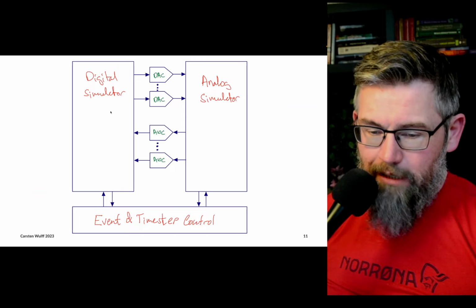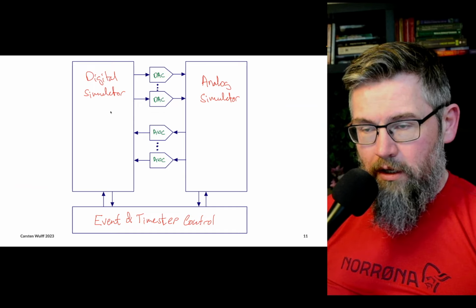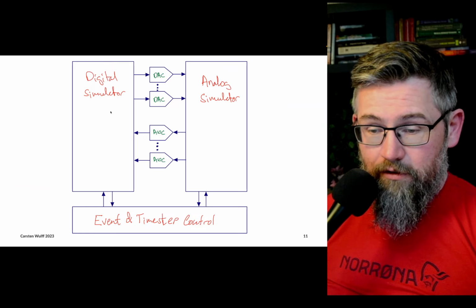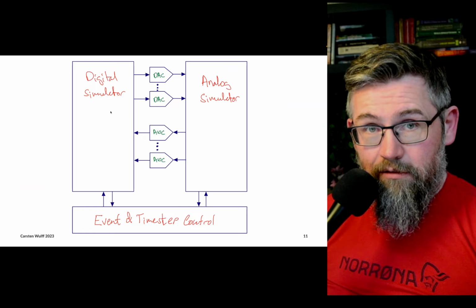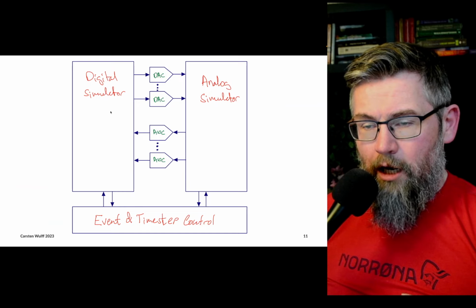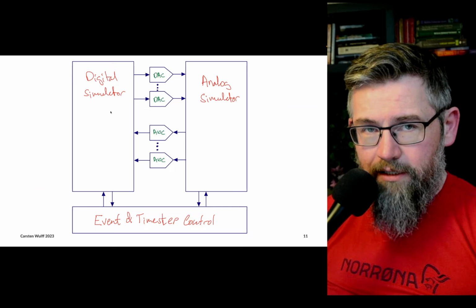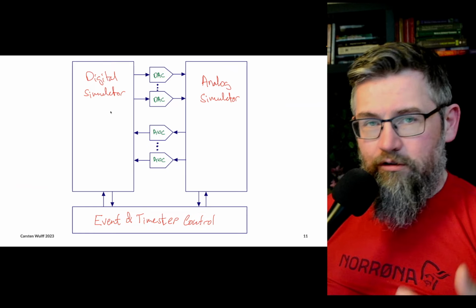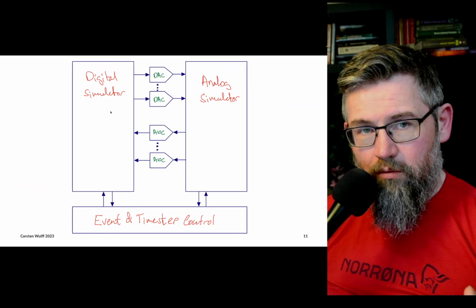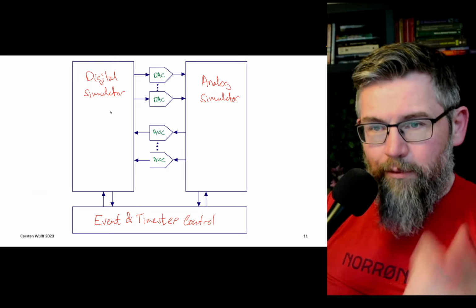And at a certain complexity level, like an ADC with a digital part, this works fine. It is a good way to verify that, for example, for a sigma delta, your decimation filter works well with your ADC. However, when you go up to chip level and you have maybe 50 analog IPs and you have hundreds of millions of gates, it breaks down. You can't do anything because it's too slow. It doesn't work anymore. So then we have to have something different.